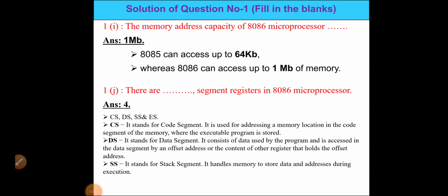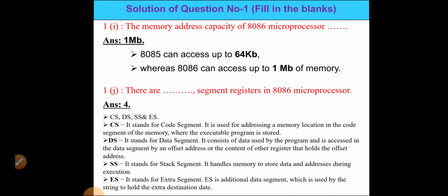SS stands for the stack segment. It holds memory to store data and addressing during the execution. ES stands for extra segment. ES is an additional data segment which is used by the string instructions to hold the extra destination data.